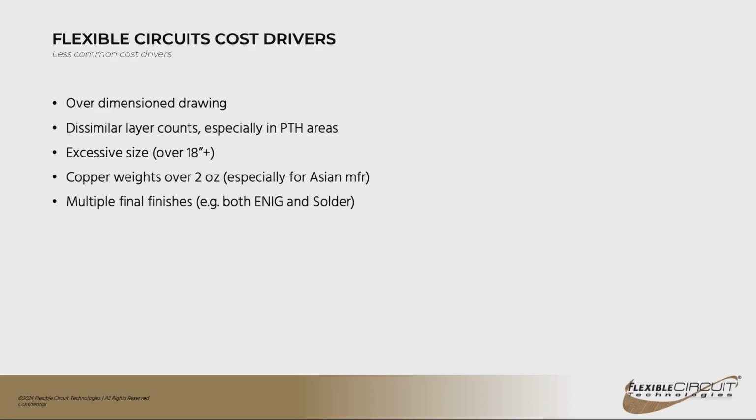So I would highly recommend doing that. If you're using the LCP to seal your circuit, I would recommend using Teflon instead, because we can get Teflon that has a treatment on it that allows us to use a thermal setting adhesive to bond it on. So I would try and steer away from LCP whenever possible, because even the manufacturers of the LCP will tell you that it's a real bear to work with. So anything that's difficult to work with typically equals lower yields and therefore higher cost.